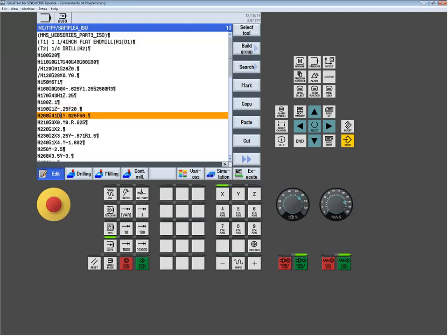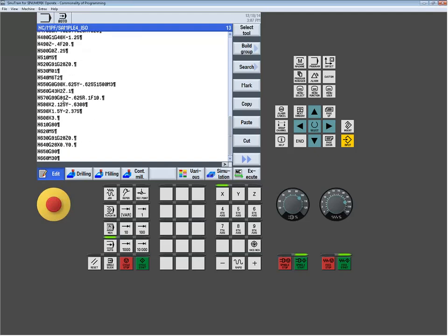This one's using cutter comp, walking around the profile of that part, but we're going to even get to drilling. You're going to see there's your standard G81, your Z, your R, IJKs, depending on the cycle you're in. A lot of times when somebody asks what cycles are going to work in this mode, general rule of thumb, anything G99 and lower will typically work.